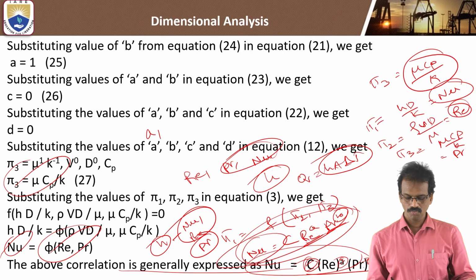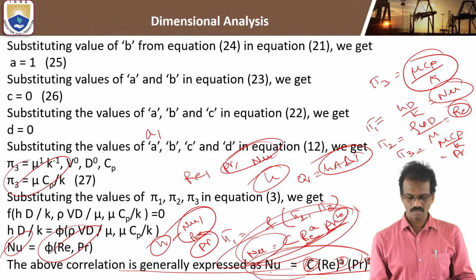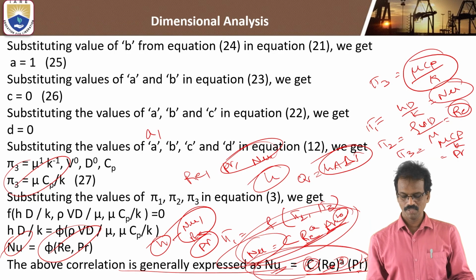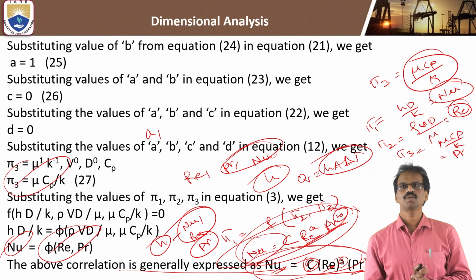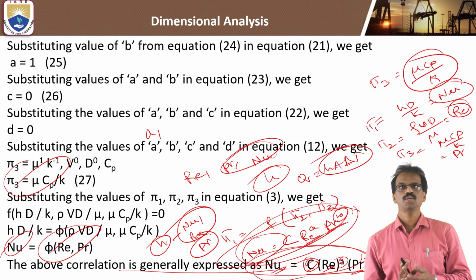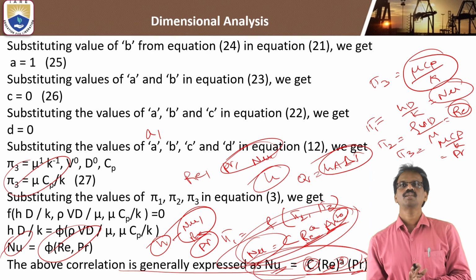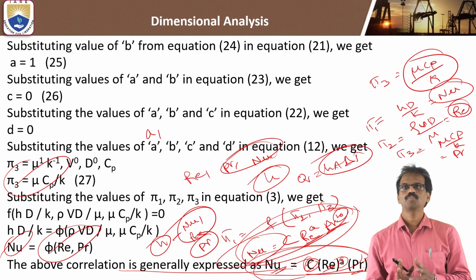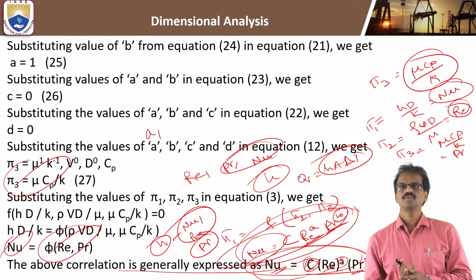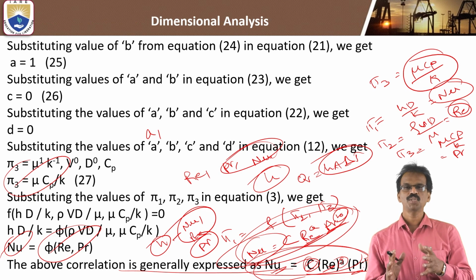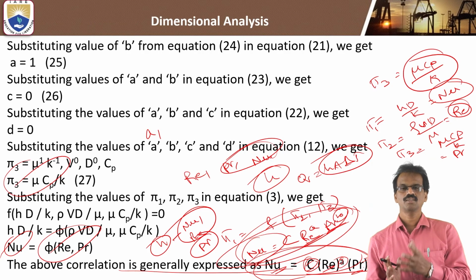So finally, if you want to study forced convection, finding the Nusselt, Reynolds and Prandtl numbers is very important. In this way, we can solve different numericals of the convection process by using dimensional analysis. Finally, dimensional analysis is a very important method to convert all the parameters into influential dimensionless numbers. By using those numbers, we can study forced convection or free convection.